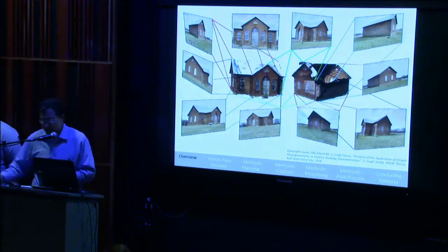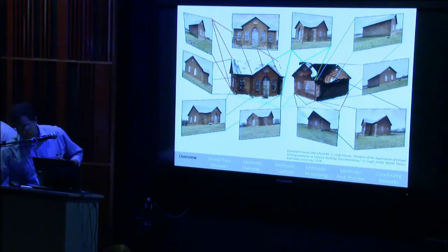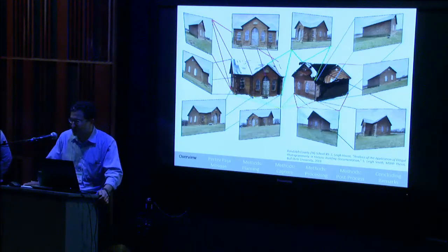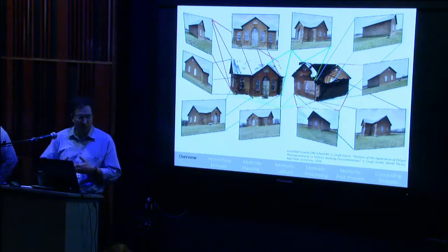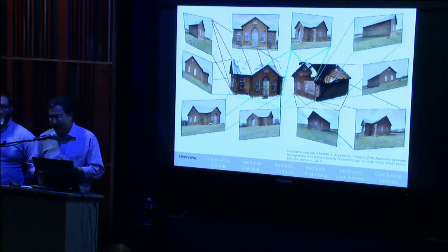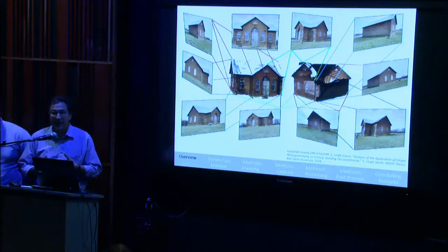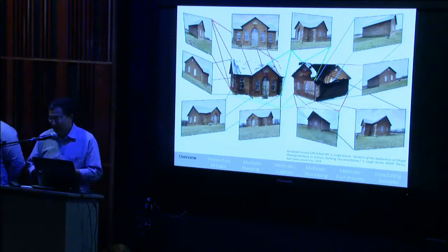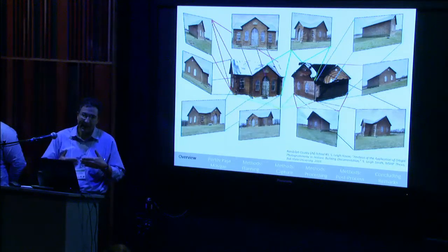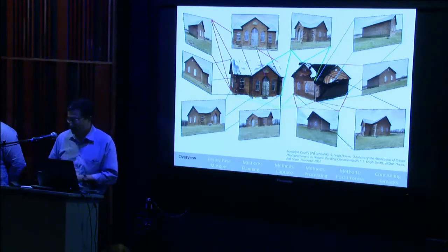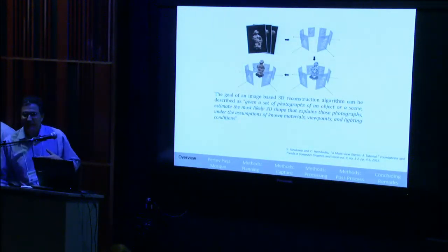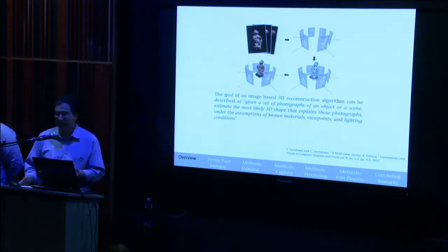One of the biggest significant developments that we have right now, and we've alluded to it in several of the previous presentations, is this idea of using photographs to develop highly accurate three-dimensional digital models, and doing this through a series of two-dimensional photographs. And the idea of this, what we call convergent photogrammetry, is that these multiple viewpoints can be correlated to create a three-dimensional representation.